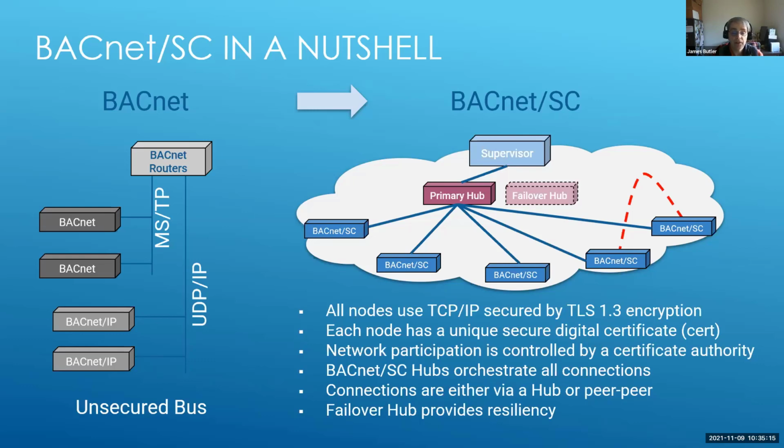To use BACnet/SC? Well, companies will be offering products that do routing between BACnet/IP and BACnet/SC. There may already be products on the market that do that. This is just another kind of BACnet router, and it will allow you to easily migrate your systems at a pace that makes sense for you. So I think that's probably enough on BACnet/SC. Jim, I'll turn it back to you.